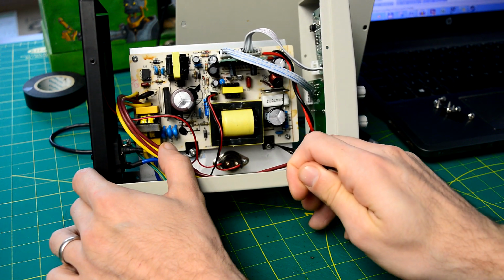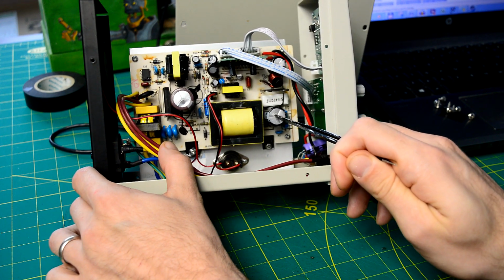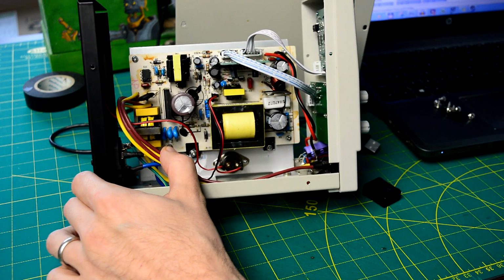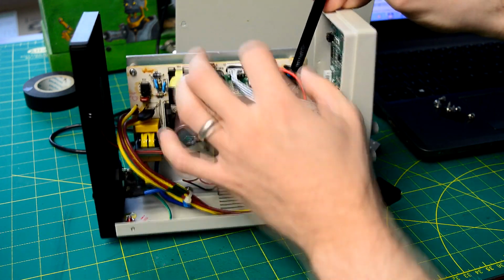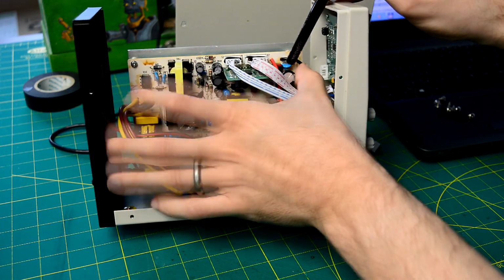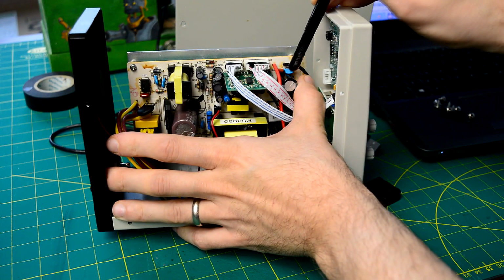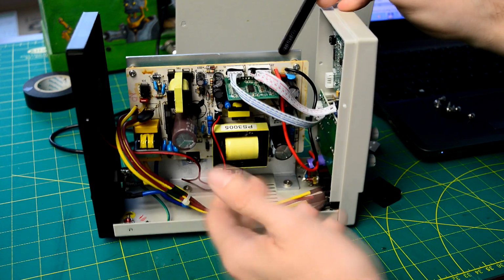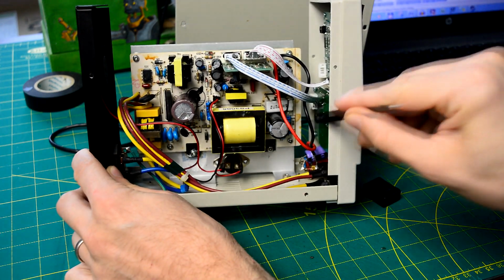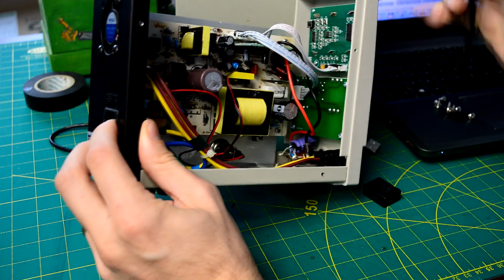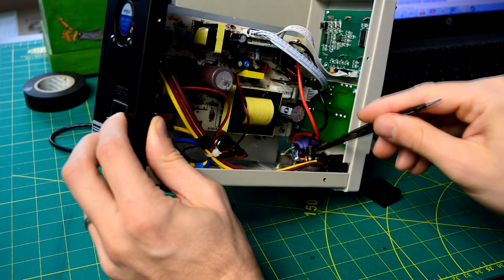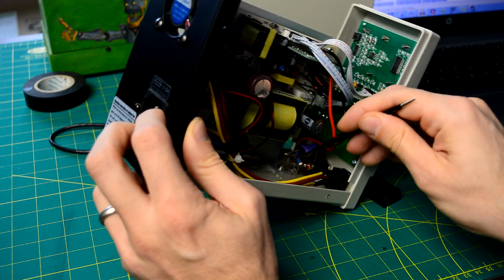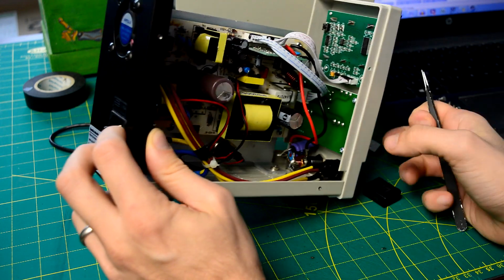So here's the rectifying diode for the secondary, first filtering capacitor, a permanent load, an inductor filter, another electrolytic capacitor, and here on top, I'm not sure how well it's visible, we've got our first capacitor, which is connecting the ground to the earth. So this screw is connected to the casing, which is connected to the protected earth. And then we got a bit of wiring going to the output. So here are the two connector plugs that go outside. And here again, we have some capacitors which link the two wires to the protected earth.